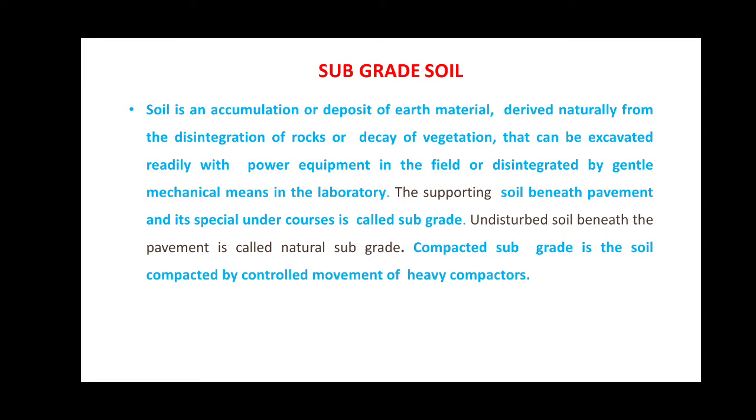A subgrade with low stability requires thicker pavements in order to protect it from the traffic loads. And the variations in the stability and volume of the subgrade soil with the moisture change are to be studied, as these properties are dependent on the soil characteristics.